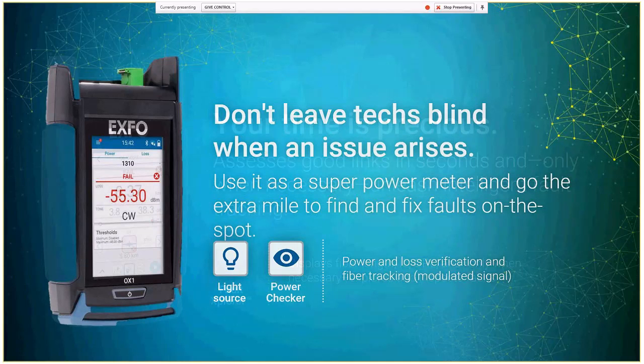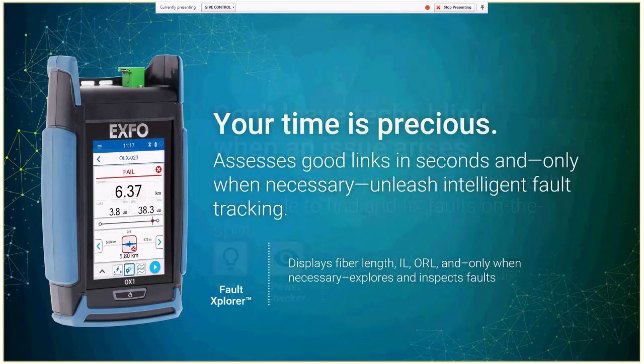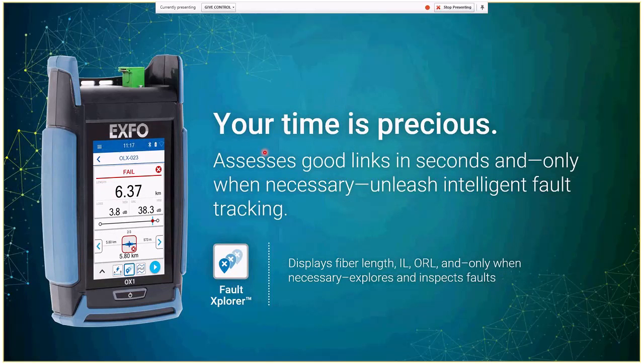So let's imagine this case where you go to the customer's house and you have a fault. You go with the power meter and you have power loss. The ONT is above the threshold. Let's say the threshold is -29 and you have -35. So what are you going to do? What do you do nowadays? Nowadays you investigate. Perhaps you're going to use a VFL, or you're going to call someone with an OTDR, or you're going to pick up your OTDR.